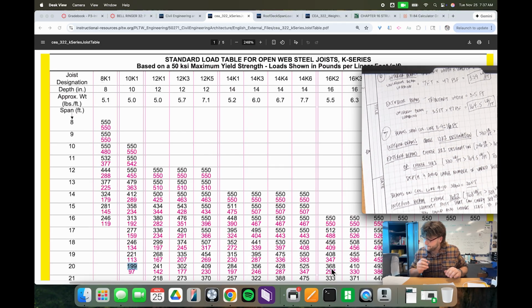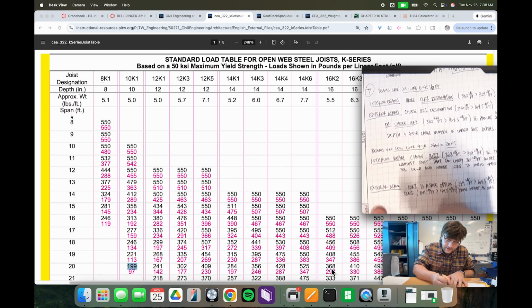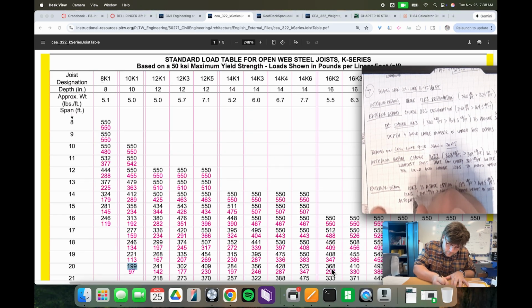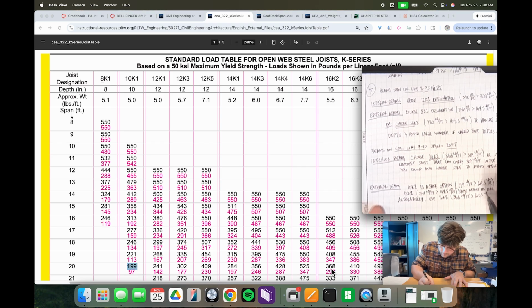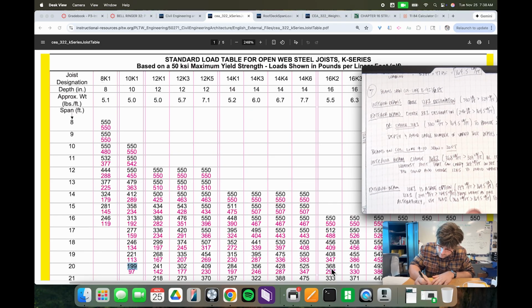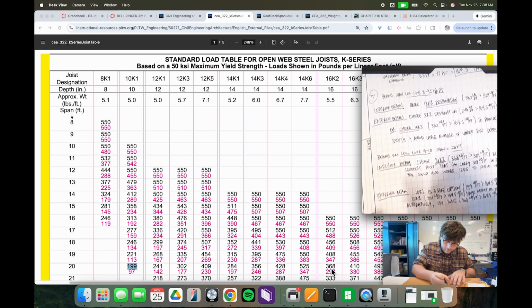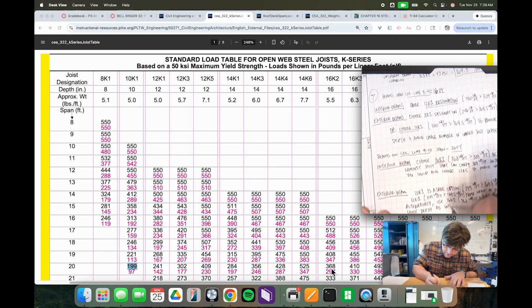But since we already, and so that would work well too, because we can put that down too. That 12K1 was already used previously. And then what we can also do is alternatively use 16K2. And then in 16K2, that's 368 pounds per foot, which is greater than our 164.5. To provide same depths as the interior beams, right?